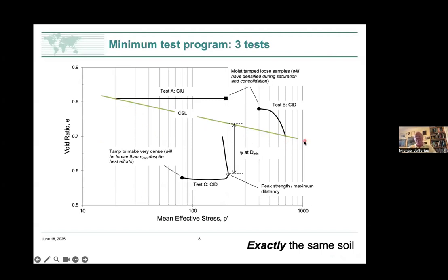Joining those two endpoints gives me my critical state locus. I also want to know my strength properties. Now, I can get the strength properties from the stress ratio at the end there, but at that point, I've taken a sample, in this case drawn starting at 200 kPa, and my critical state is at 20 kPa, so my transducers are losing accuracy. In the case of this test here, the critical state will be at about, well, heading towards 20% axial strain, at which point the sample is bulging and we have a lot of area correction. So again, it gets to be uncertain.